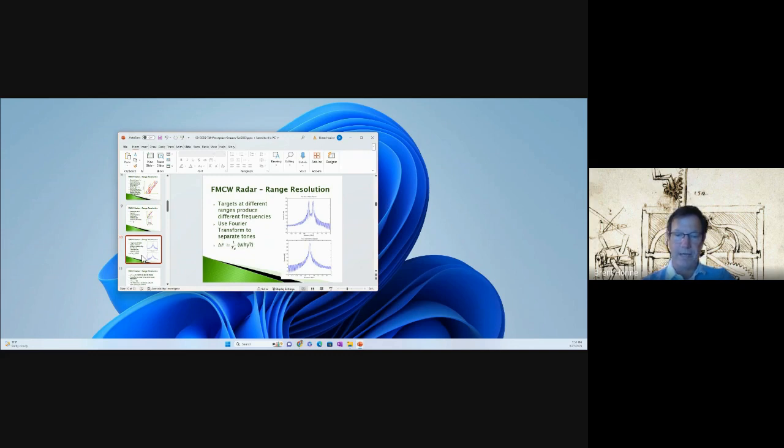All we have is amplitude versus frequency, and we can divvy up that frequency and get better and better resolution, but we don't have any time resolution. Now, wavelets and other types of transforms maybe give you a trade-off, but that's the interesting thing about Fourier transforms: they trade off resolution completely from one domain to another. So it's an easy way of thinking about it.